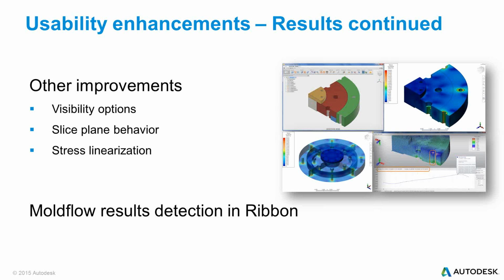This is a really important improvement for us because it helps to make sure that the results that you get, you can reuse them to make sure you are code compliant with the ASME pressure vessel code. Previously, the primary bending stress was not reported, and we only reported the primary stresses based on the maximum shear stress and not the von Mises stress method.